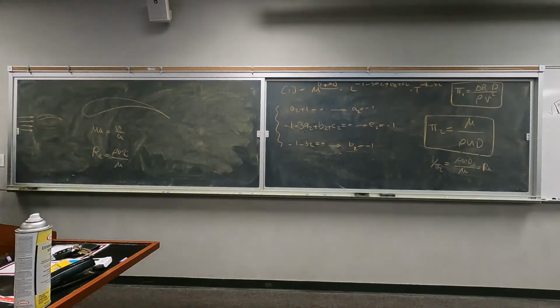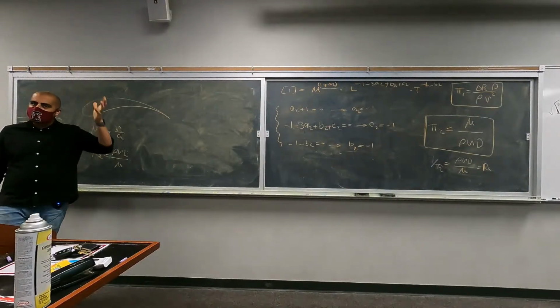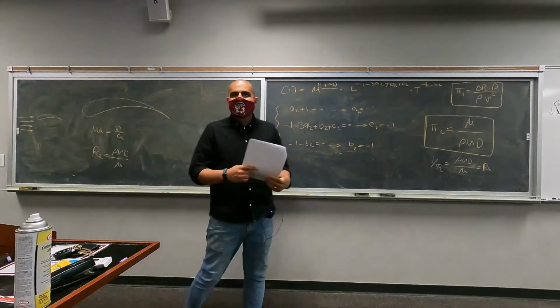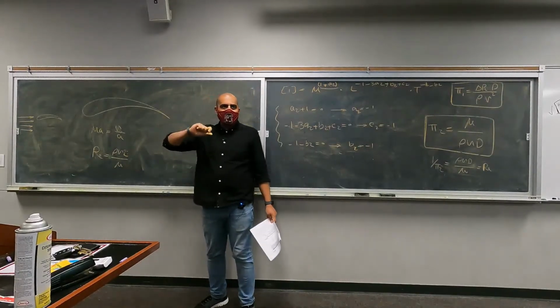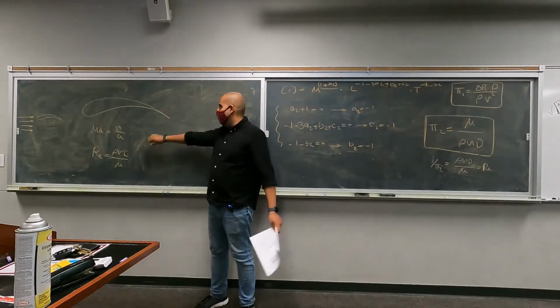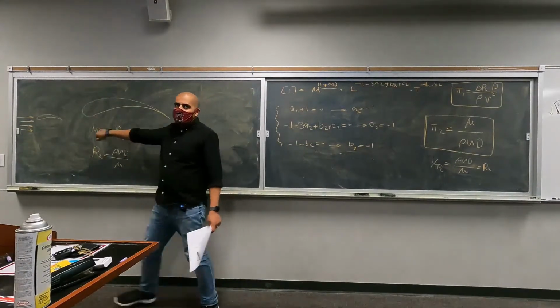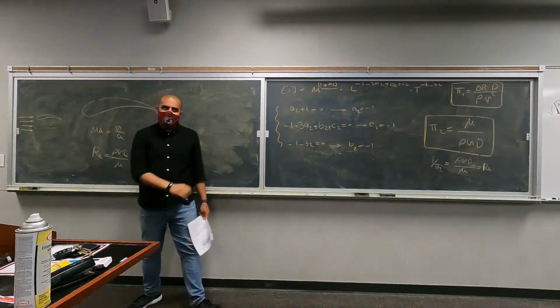If you are doing the analysis inside the wind tunnel, you can use the same results for designing a real-world aircraft, a real-world wing with the huge dimensions, as long as that real-world case, or the operational velocity of that real world, has the same Mach number as your test section and has the same Reynolds number as the test section. Does this make sense?